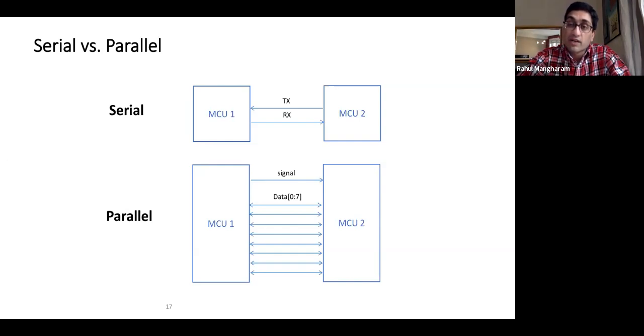Yes, if you have a larger die size, you have to power on bigger transistors, and bigger transistors will consume more power. So that answer is also true, but the main problem is that when you are fabricating silicon, you have a certain yield of the silicon actually coming out pure, without any impurities. And there's a probability of an impurity. So the larger the area you go to, the higher the probability that you have impurities in that die size, and then the yield goes down.